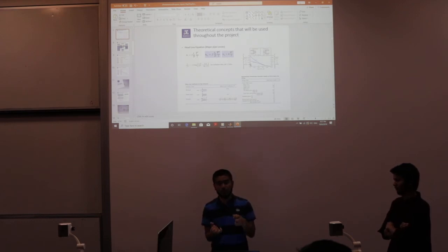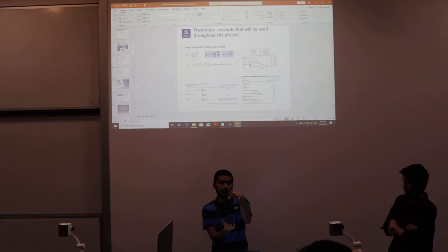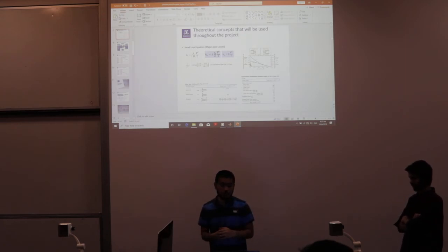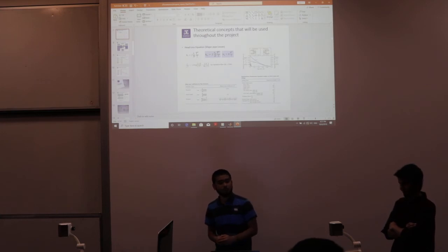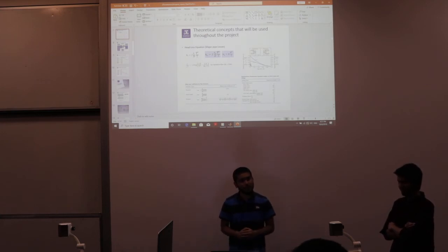So what we did was we tried to design a mold or a clamp to join these two pipes together. The clamp is also made out of PVC pipe, so that the two pipes and the clamp can be glued together and bonded permanently to ensure that the pipes are straight and also leak-proof. Does that answer your question? Alright, thank you very much.